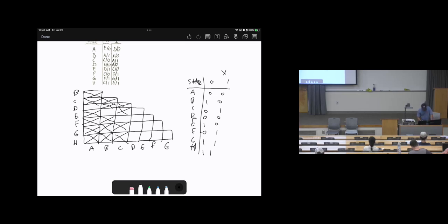Okay? Now with state D, here is D, then between E, F, G, H. Is there any similarity? 0, 0, 1, 0, 1, 0? No. Then cross everything. Cross all of this column. Then we have E, F, G, H. Here is E, 1, 0. Here is 0, 1, 1, 1, 1, 1. They are not similar. Therefore, cross all of this column.